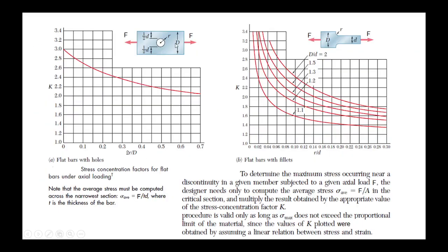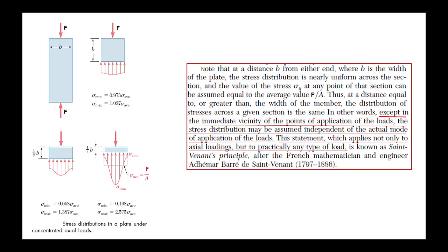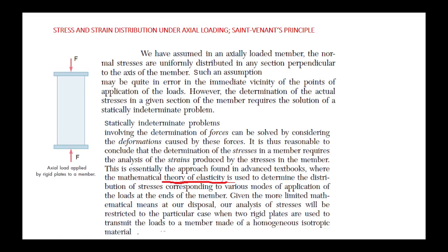If there is a discontinuity over there, to be able to find the calculation more accurately, I said use a finer mesh. Okay, for having a finer mesh, not the same mesh size. If there is no abrupt change, no discontinuity, use a greater mesh size to decrease the runtime, to make the computer usable for such a solving.